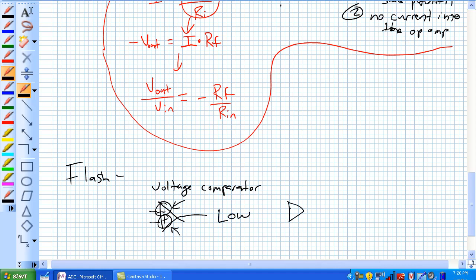You can also put them up this way. So let me give you an example here. If that's 8 and that's 5 volts, what's the output of this guy? Well, its non-inverting input is exceeding its inverting input, so it's a high. Now, what's that? Well, it's not the conditions we're looking for, so that's a low. Okay? So that's how our general purpose voltage comparator is used. And we use these in the 555 lectures.